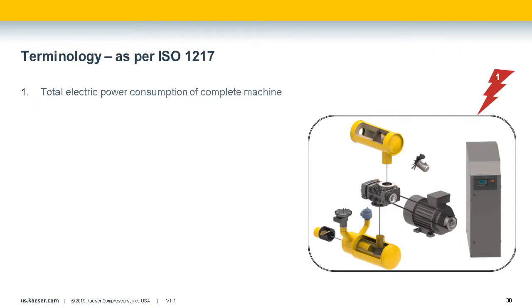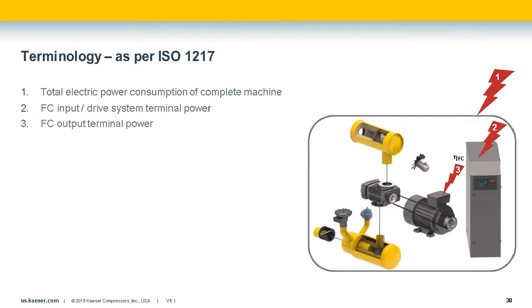The performance of the air producer is only part of the story. The air must be drawn through and pushed out of several components. Each of the components in the package represents a flow loss, pressure loss, or a rejection of heat. To permit objective comparisons of different offers and related performance specifications, it is important to understand the different reference points of the flows and performance and the correct terminology. Otherwise, there's a risk of comparing apples and oranges.